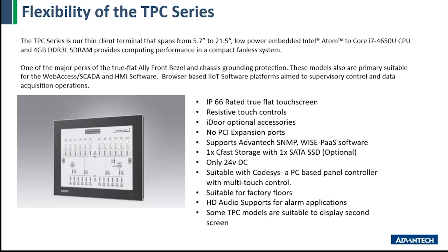Compared to the PPCs, these ones actually have a CFast and mSATA connector. As you can see here with the SATA SSD optional, the back of the unit is actually quite thin, and the way for you to get an SSD into that is to buy an expansion kit for the unit. So in terms of lead times, it can be a little bit of an issue where if you require an SSD, you do have to buy an extra part for it.